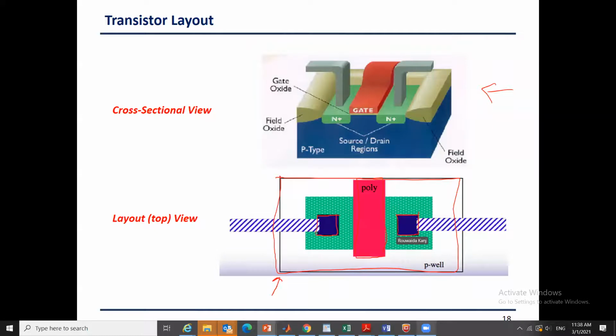The source and the drain diffusions will be here, but if I shower it, when the ions bump into the poly, nothing will happen. Things will happen around the poly. And if I want to draw a wire, then it should have the shape of this wire and so on and so forth. So each color code is a color code for a layer. Okay, so the color coding is for a layer and is for a mask. Okay, one layer, one mask. That's the bottom line.